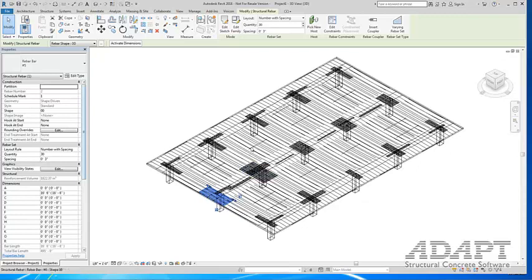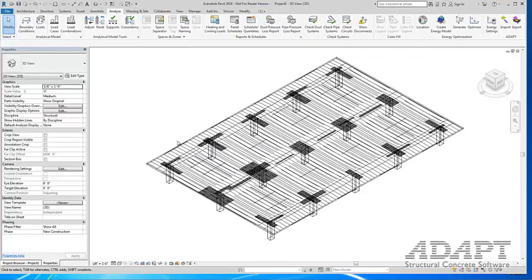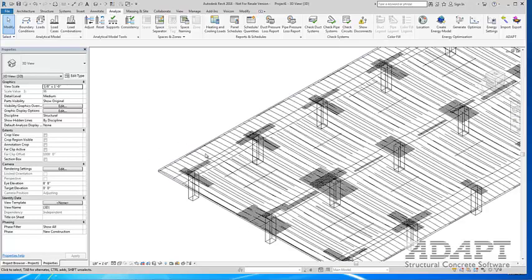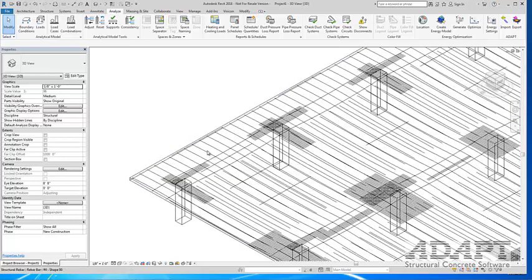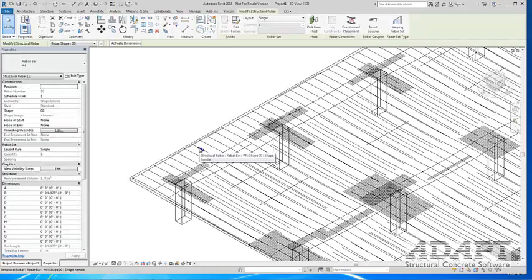If I select, for example, a distributed bar, these are distributed bars that can then be manipulated within Revit for the pre-processing of generating the structural plan data. In terms of the post-tensioning, you can see that the post-tensioning is actually represented as segmented reinforcement. So each segment, if I click on this particular